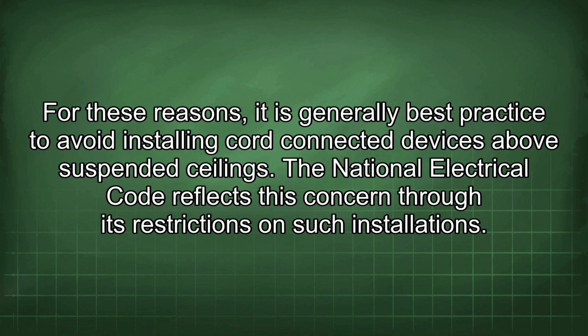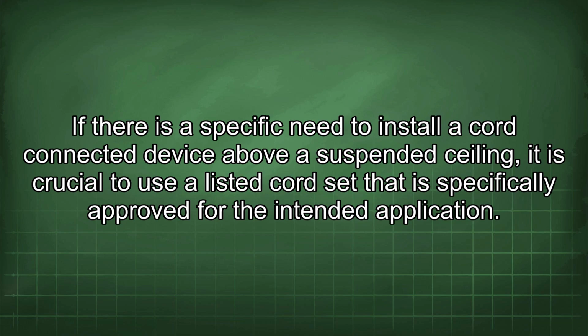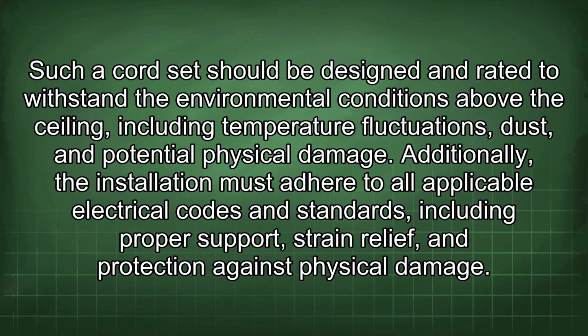The National Electrical Code reflects this concern through its restrictions on such installations. If there is a specific need to install a cord-connected device above a suspended ceiling, it is crucial to use a listed cord set that is specifically approved for the intended application. Such a cord set should be designed and rated to withstand the environmental conditions above the ceiling, including temperature fluctuations, dust, and potential physical damage.